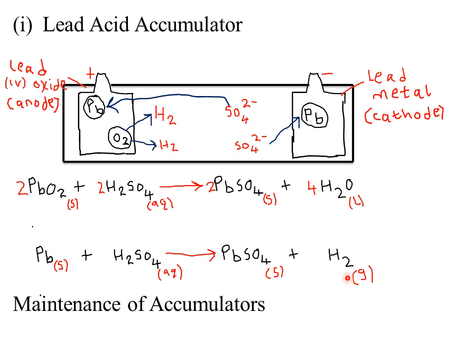of the electrons. So actually this generates electromotive force between the anode and the cathode because they are at different charges. One is highly positively charged while the other is highly negatively charged. So that creates a potential difference, or what we call an electromotive force, between the anode and the cathode. Now a single cell has an EMF of around 2.2 volts when fully charged, but this actually drops to around 2 volts when it is working.